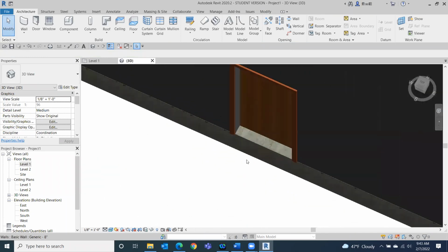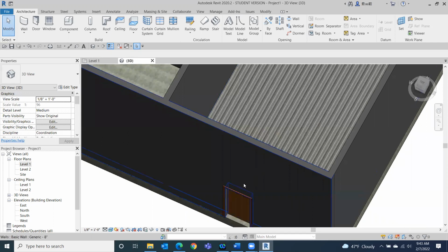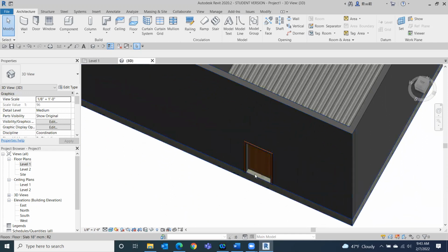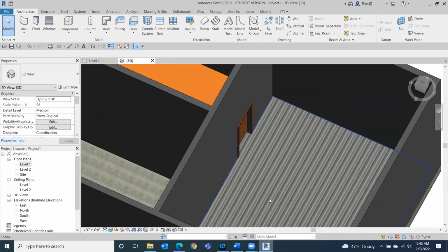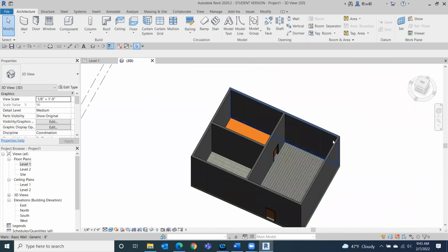So we'll have that same issue here on this exterior door, how it's going through there. We don't want to have that carpet going to the exterior door, so this one would be okay for our exterior door. But any interior doors, you want to make sure you catch that gap when you create that. So you can see it's basically you're creating the shape that you want the material to be. So it actually just takes a little practice, but it's not that bad. It's just lots of little things you need to catch when you're creating it. Any questions about that?